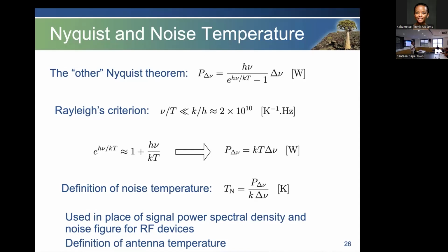Now that is a very, very useful thing when you're a radio astronomer, because there is your absolute calibration. If you want to calibrate a noise source, this is your gold standard. You have a resistor and you measure its temperature, and that equation tells you how much power you're going to get out. Also, very conveniently, because of Boltzmann's constant being in there, it's a very, very small power as well. So you can use it to calibrate your radio telescope.